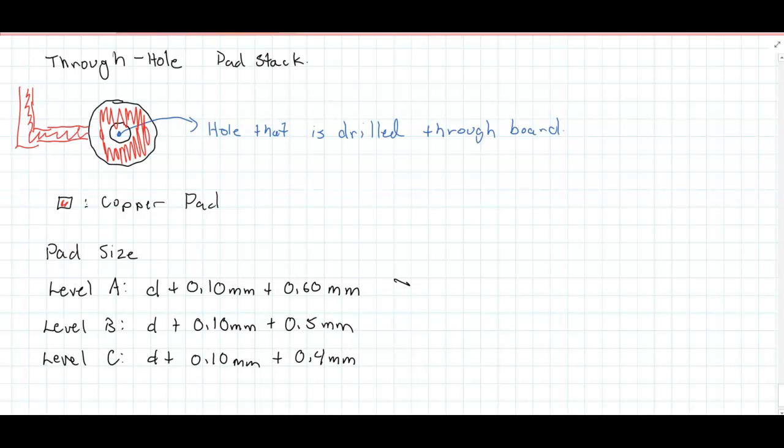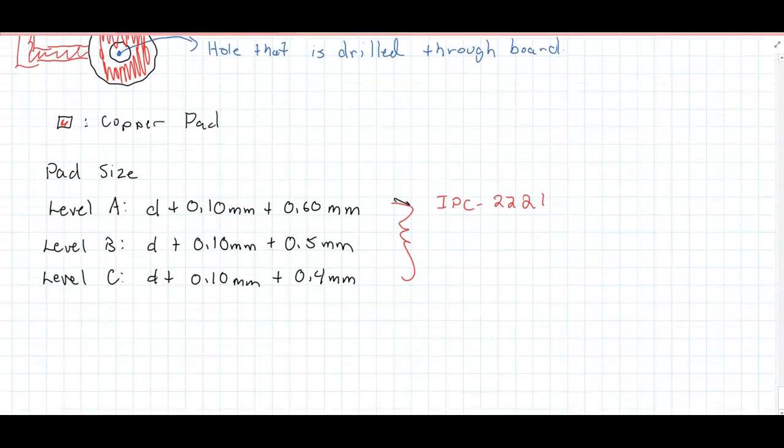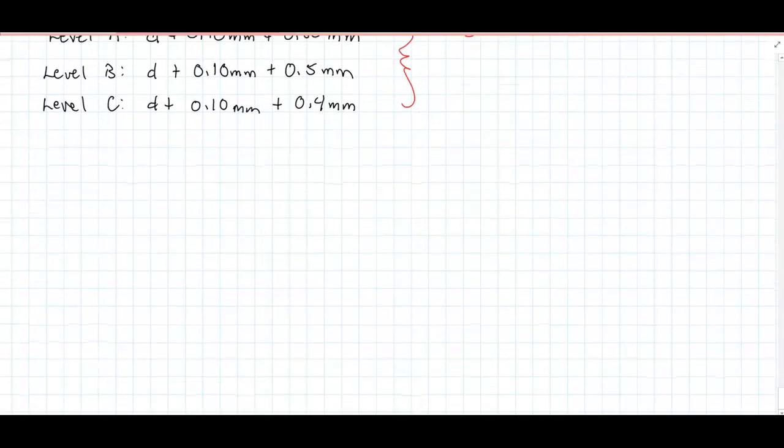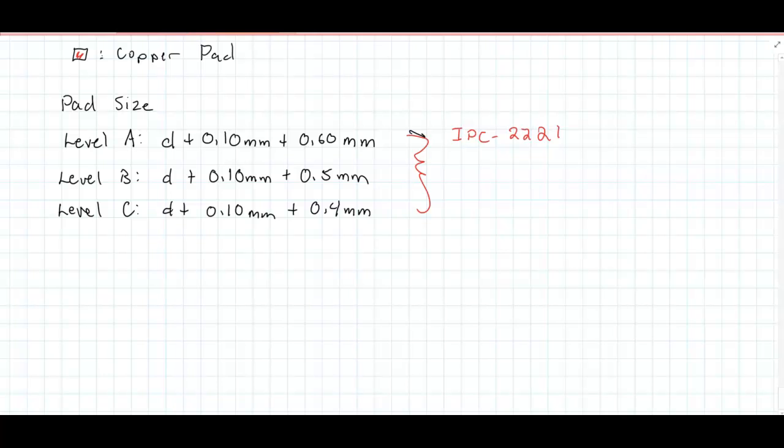And these actually come from standard IPC 2221. That's where those come from. Okay. Now, of course, we'll go through an example of this in the next video when we actually make a pad stack. And again, unless otherwise stated, for this class we're going to be using level A standard.